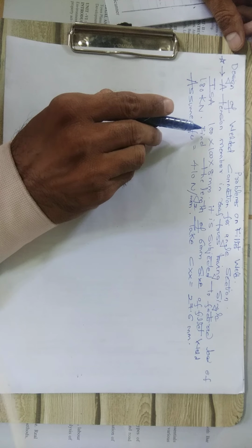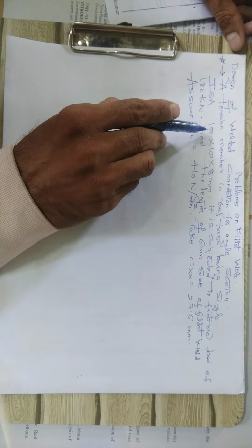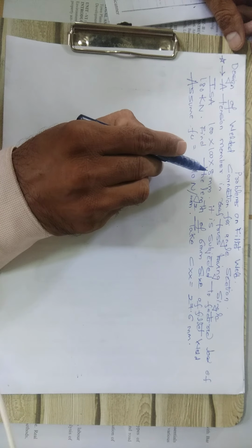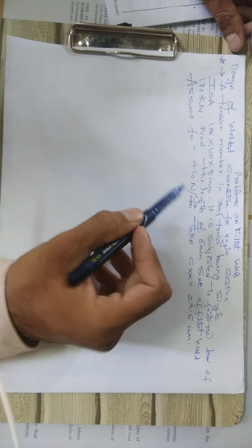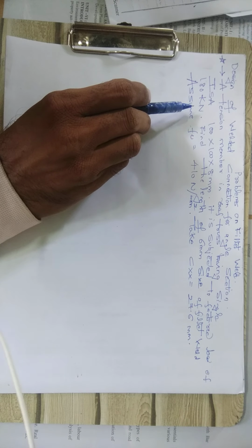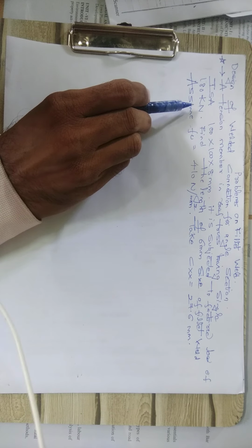The single angle section, that is Indian Standard Angle, has dimensions of 100 by 100 by 8 mm. That means this 100 indicates one side of the angle, the other side of the angle is again 100, and the thickness of that angle section is 8 mm. Again it is subjected to a factored load. This single angle section is carrying a factored load of 180 kilonewton, which will be borne by this single angle section.